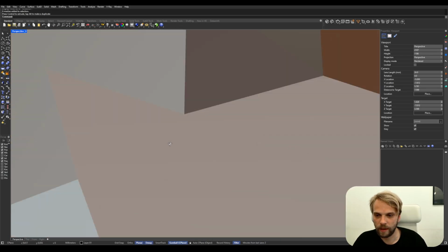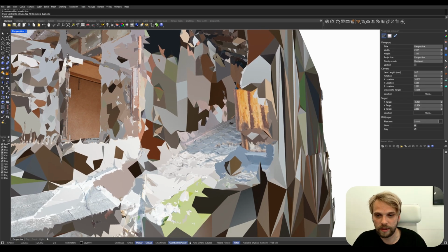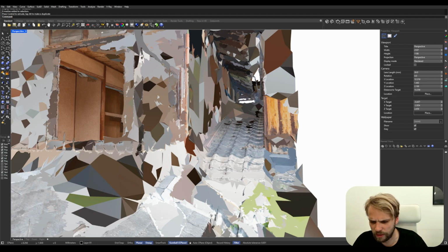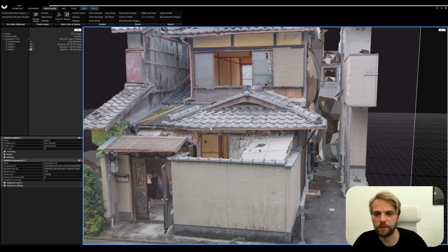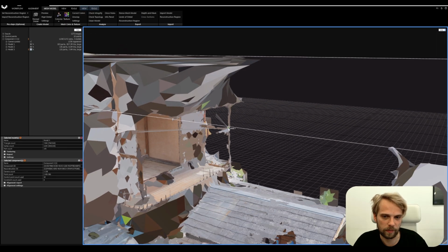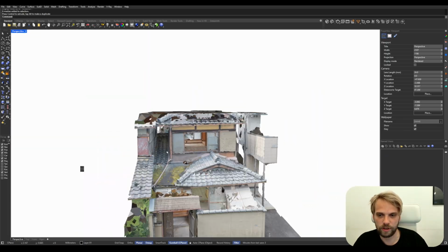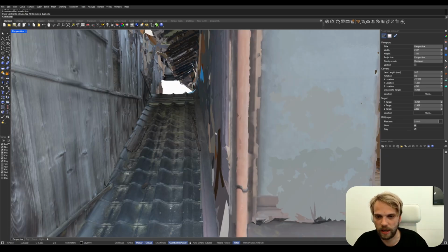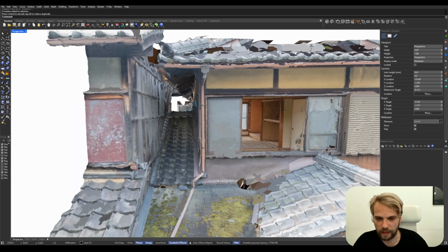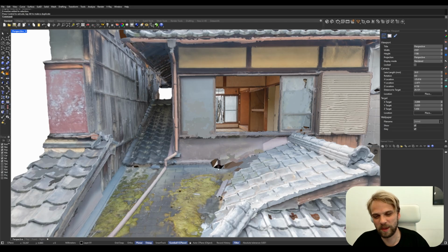The balcony. The tricky bit of the back roof, I managed to pull the detail back in with a few anchoring points, what are they called? Control points. With a few control points here in the back, point 11 being there, point 7 being there, that was sufficient to bring in the back of the roof. The front of this roof is much higher in quality, and that's because I was standing right here, and I didn't take pictures of my feet. But as I was walking around, I took a bunch of pictures of this.